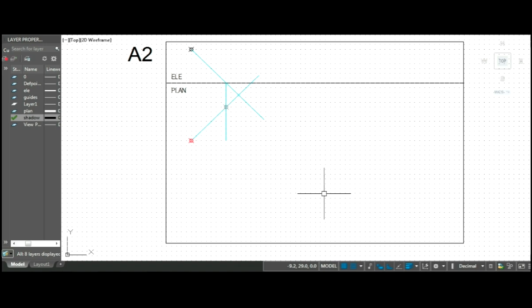To draw the shadow of a line, let us first draw the elevation of a line about 6-7 centimeters tall, the plan of which will be a point exactly under it. Like we did in the previous problem, let us draw a 45-degree line starting from the base of the point in plan and cutting across the ground plane.